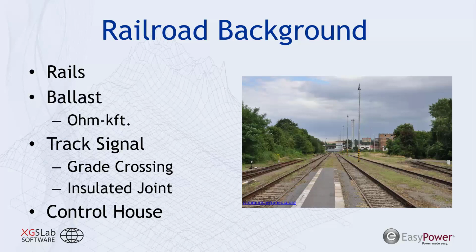They often do have a ground ring around them that can help with the concerns we're talking about with AC interference, but it's possible that ground ring is insufficient for the type of induction or capacitive or conductive coupling that you could see from AC interference or the effects of a transmission line next to a railroad.